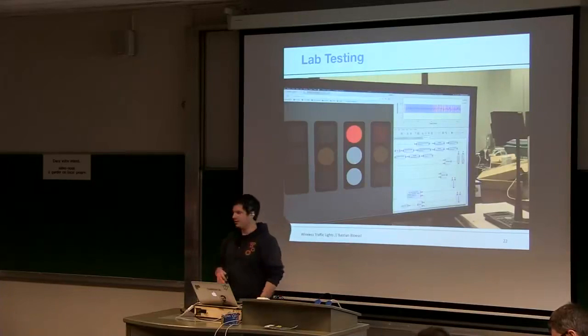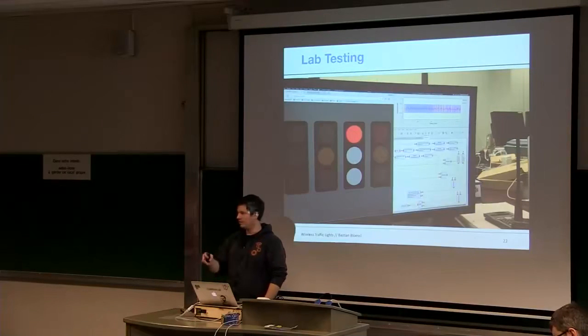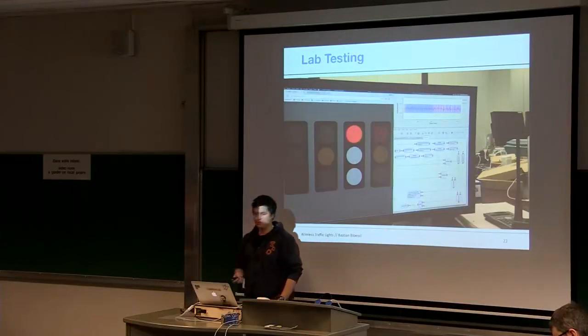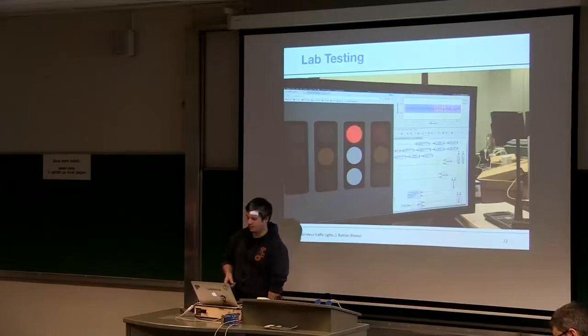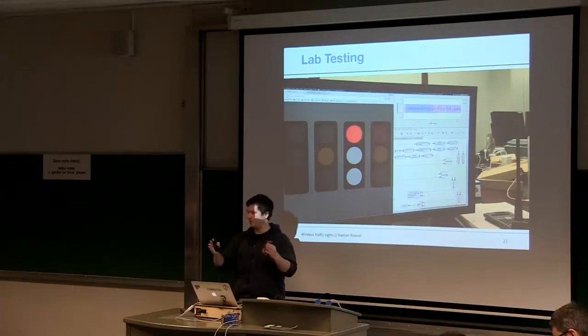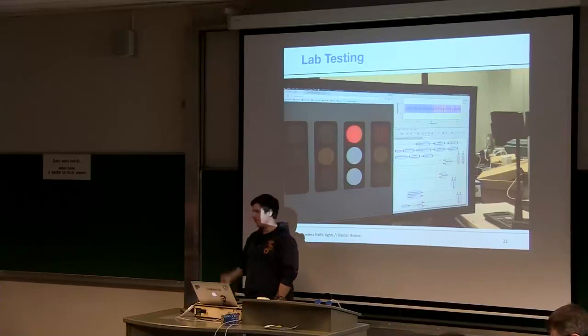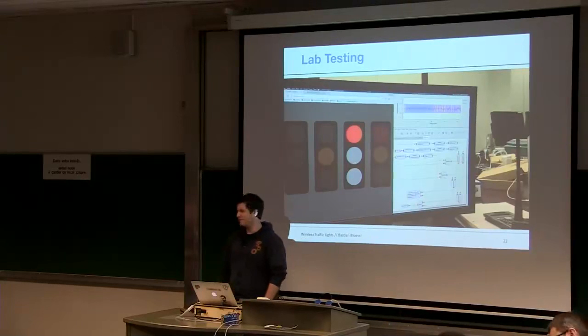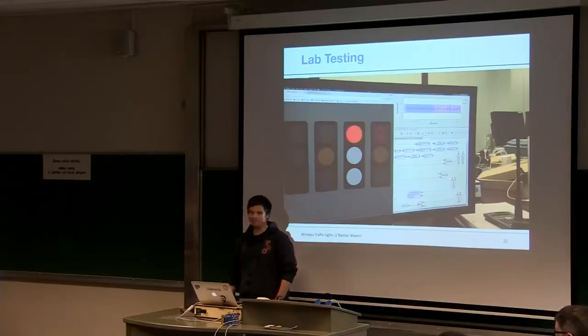And I had a presentation 2 years ago with RDS TMC. So this is the digital subcarrier on FM broadcast data. So there's also some traffic information modulated on there. So your usual GPS device gets it from the FM broadcast stations. And also I have a project which is available for decoding my car key fob, for example. Then you get the 64-bit rolling code out of it, and yeah, stuff like that. So there's tons of very, very low-hanging fruit out there where you can have some fun playing around.